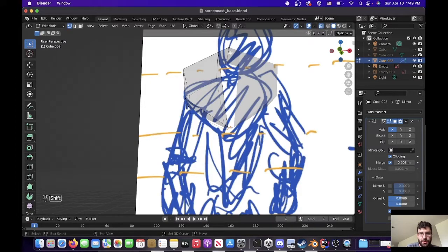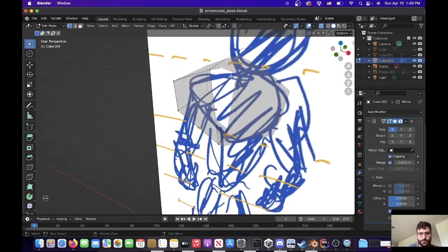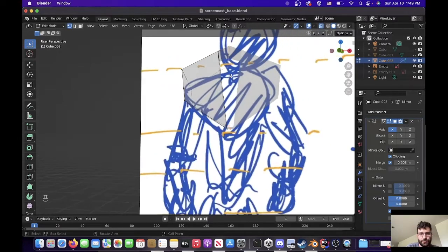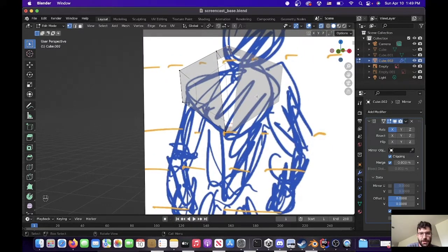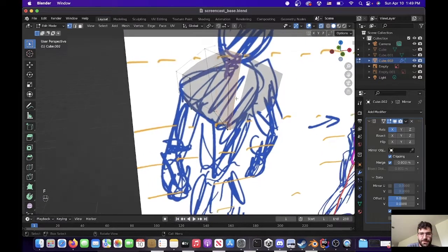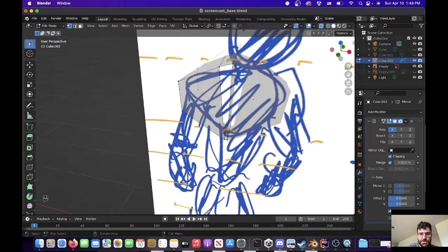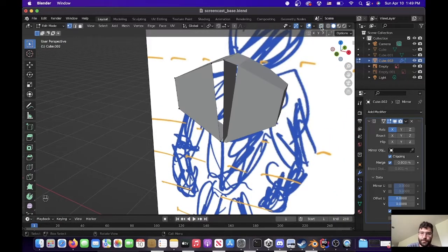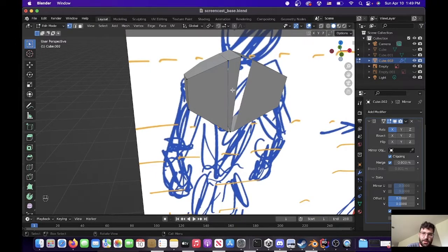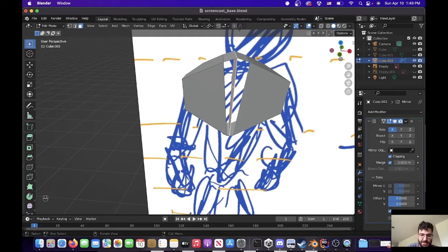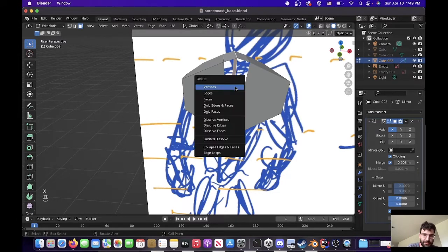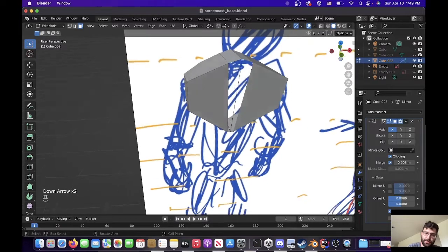We're gonna select all of these points and just hit F for fill. And all of a sudden, we just made new edges and new face data. We actually don't want this internal face. So that was a mistake on my part. So if you hit X, like cross out, delete just that face.